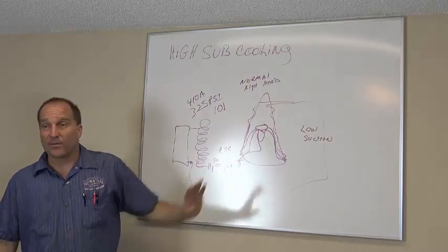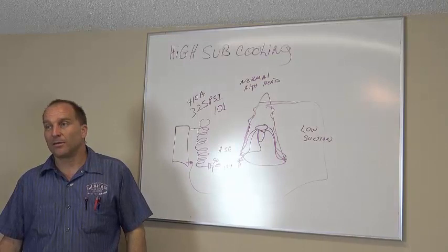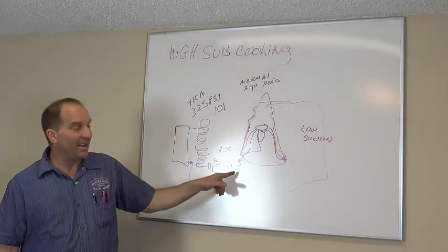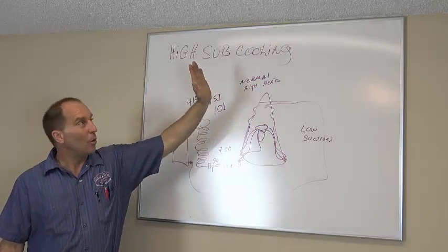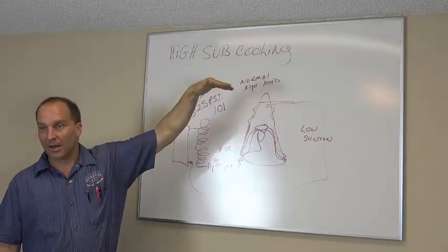If you go up to your evaporator coil and you see that the liquid line is sweating, now you know you have a restriction in that liquid line somewhere. So you may have a kink down at the bottom of your copper before it goes through your line, or at the top plate where it bends over, somebody kinked it there. And that'll cause that restriction.